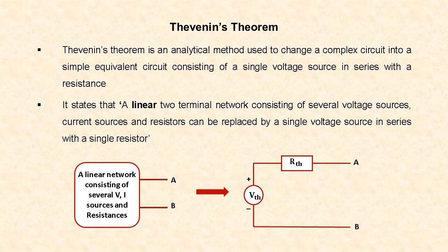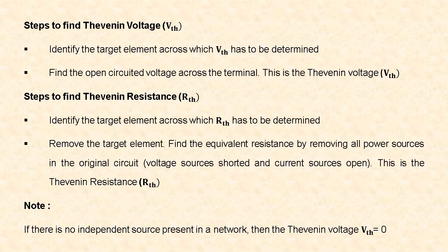This Thevenin's theorem is especially useful in analyzing power systems and other circuits where one particular resistor, that is the load resistor, is subject to change. Now let us see how to find the Thevenin's voltage. First, identify the target element across which the Thevenin's voltage has to be determined. Then find the open circuited voltage across the terminals. This voltage is the Thevenin voltage.